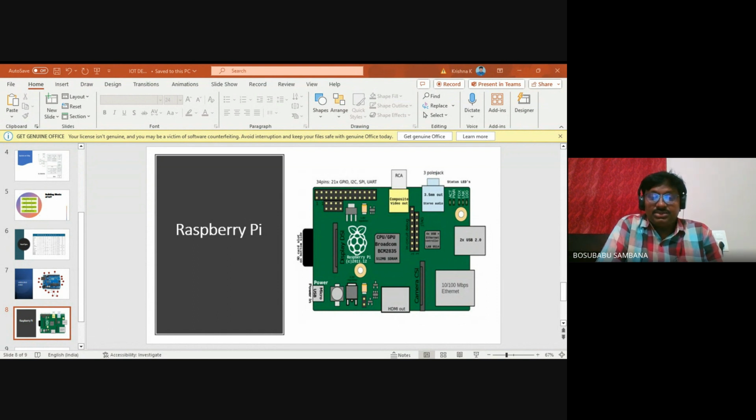The Ethernet adapter plugs into a different USB port on the motherboard. The USB port in the Model A Plus and Pi Zero is hardwired to the system on chip, while the Pi 1 Model B only has two USB ports. The USB Ethernet chip in the Pi 1 Model B Plus and later models includes a 5-port USB hub, of which four are usable. A micro USB port serves as the Pi Zero's USB connection to the SoC.